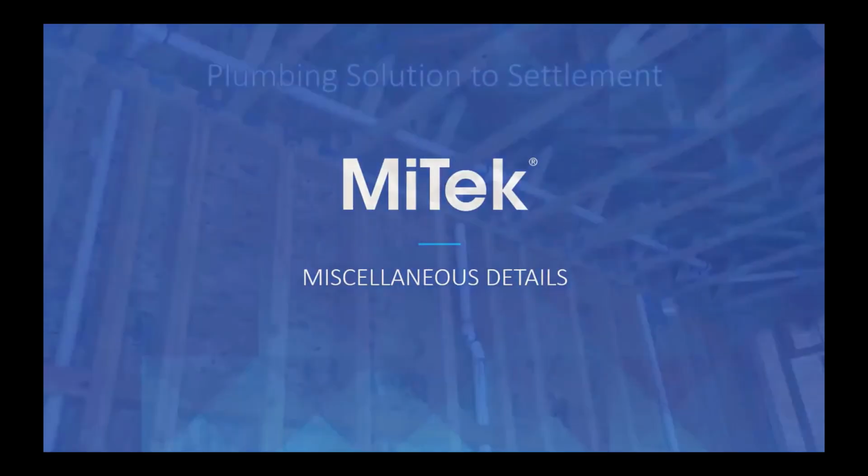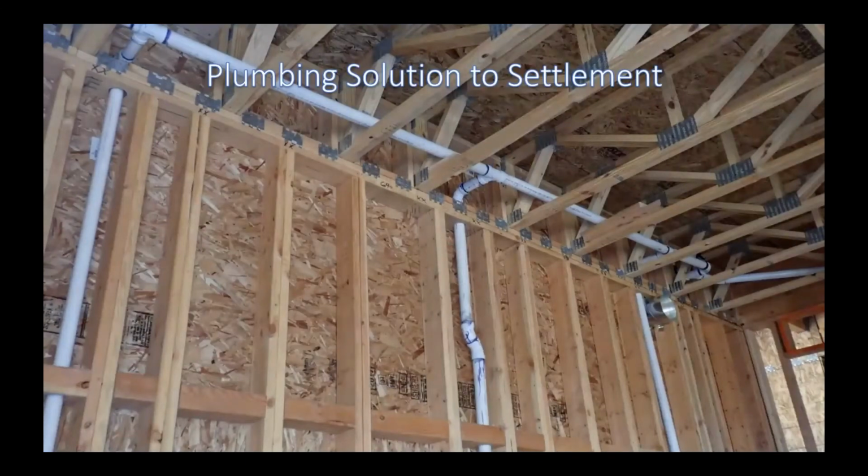So just in closing, some other light miscellaneous details of things that I did see over there. To take account of building settlement and potential movement coming down across the 6 stories, the plumbing often has a lot of bends here and there to try and take up any future movement of the building, although there shouldn't be a lot. But if you provide them with different bends and returns, they are much more flexible than a straight, long, uninterrupted shaft. So that's the way they deal with them. They do work with some limitations, but the services are really not an issue. Once you get into the scheme of things, it's not really hard to do. So you just provide a number of bends to deal with those sort of things.